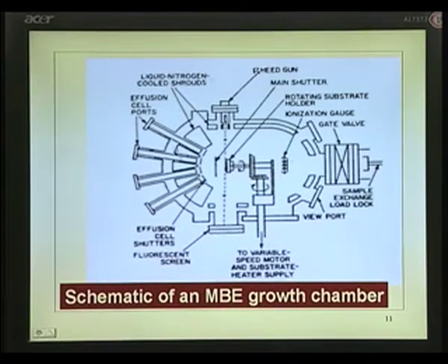So, those are the key things for getting this high vacuum, and also before turning on the system, the entire assembly will be put in a huge oven which is heated to degas the system. All that preparation of this chamber itself will be a big job. You must spend a week before you start growing the layer, okay?